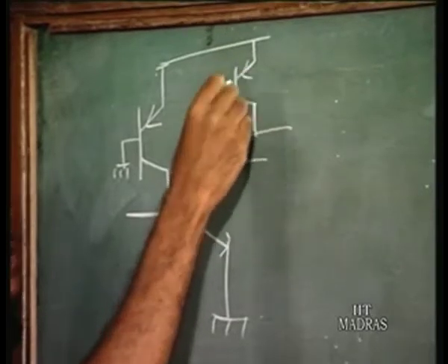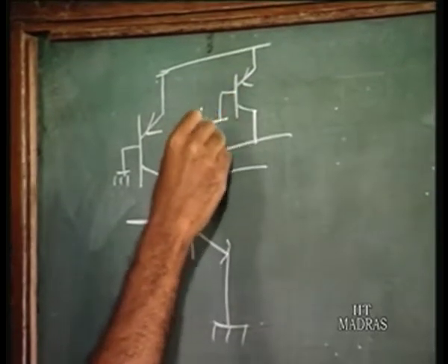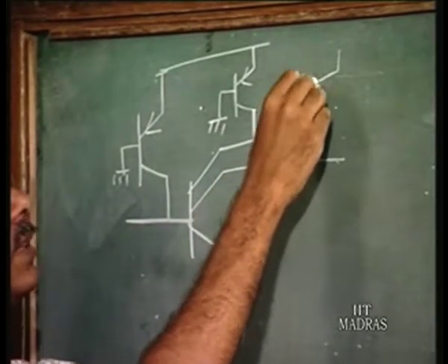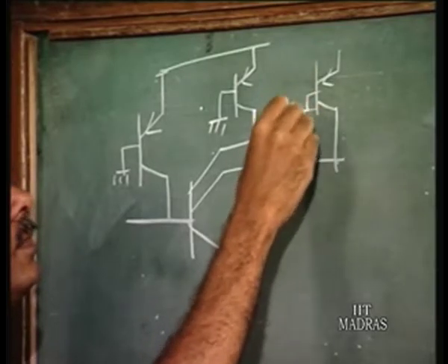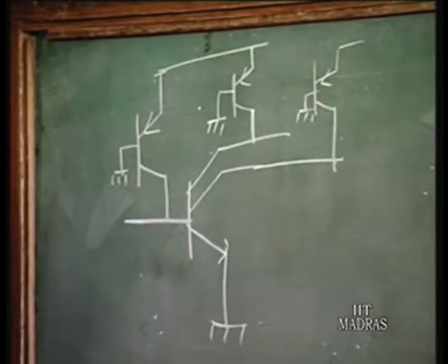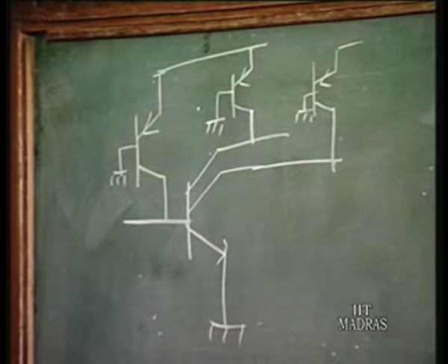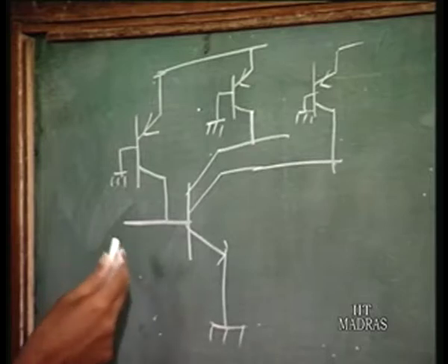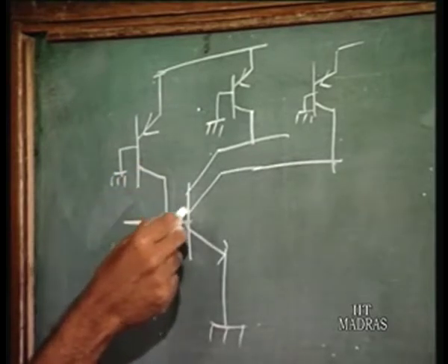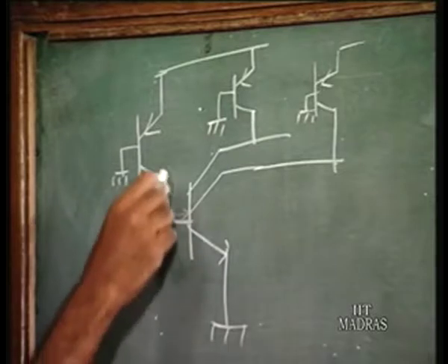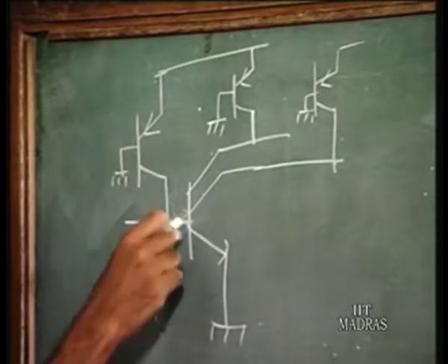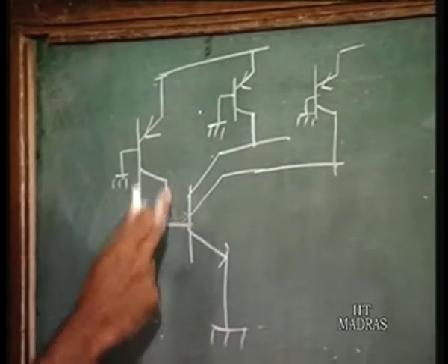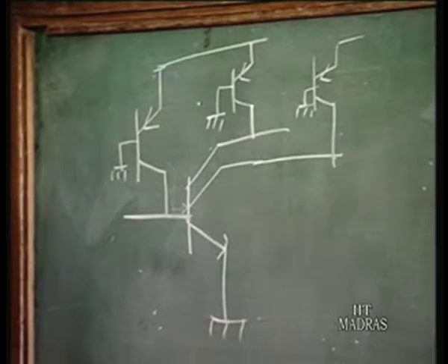This is going to some base, so you have another PNP here. All the collectors will have some PNP at the base. Now if this input is high, or you have a cutoff transistor basically here, then what happens is the collector current of the PNP goes in as base current, and this base current must be sufficient to drive this transistor to saturation.